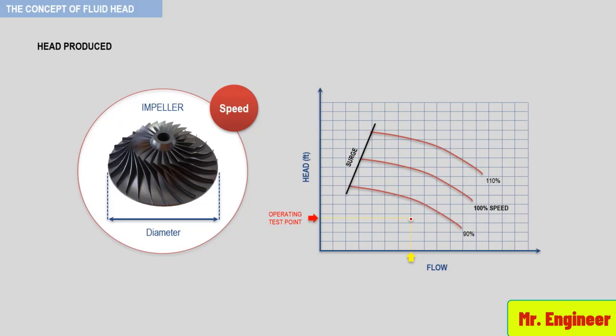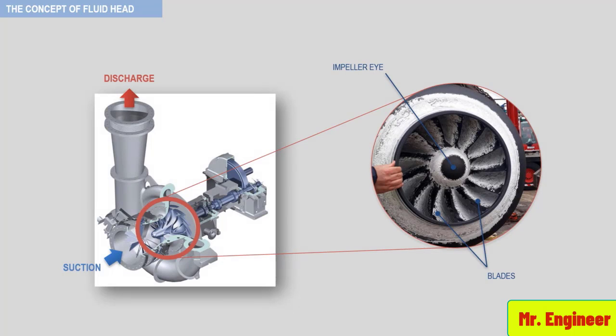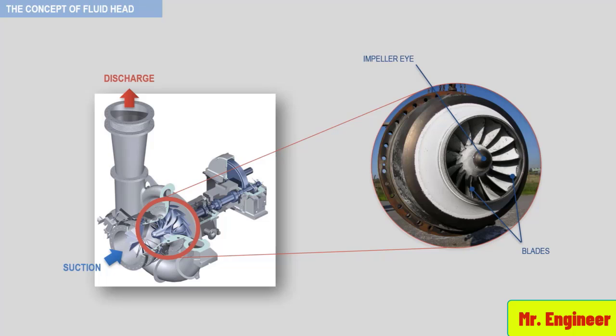The following pictures will show a case of a fouled compressor that we have experienced recently at our plant. You can see here the impeller severely fouled with dust and fines that were carried out with the process gas following a dysfunction in one of the filters upstream of the compressor. Here the same impeller is seen from a different angle.